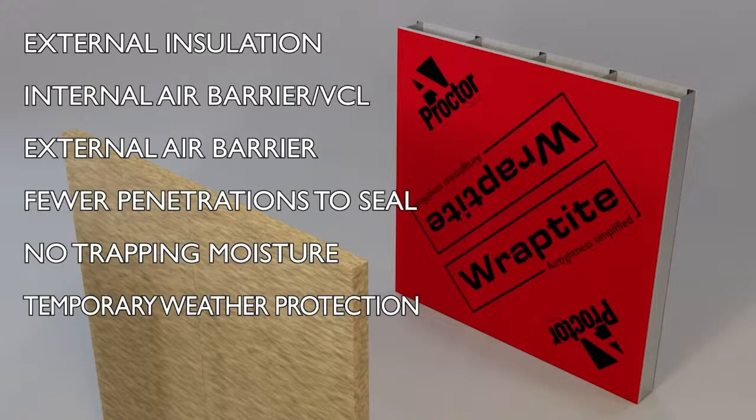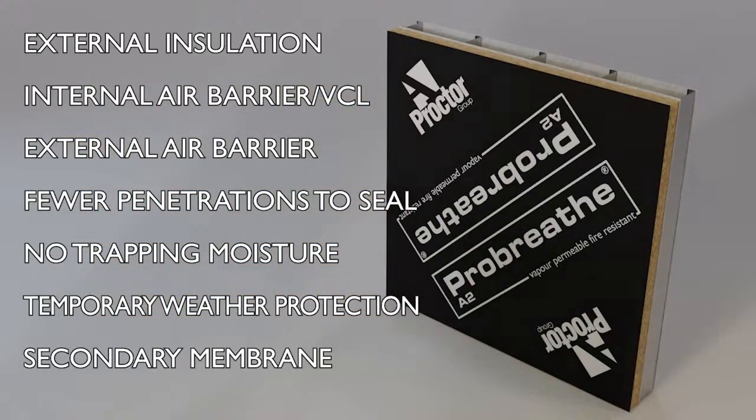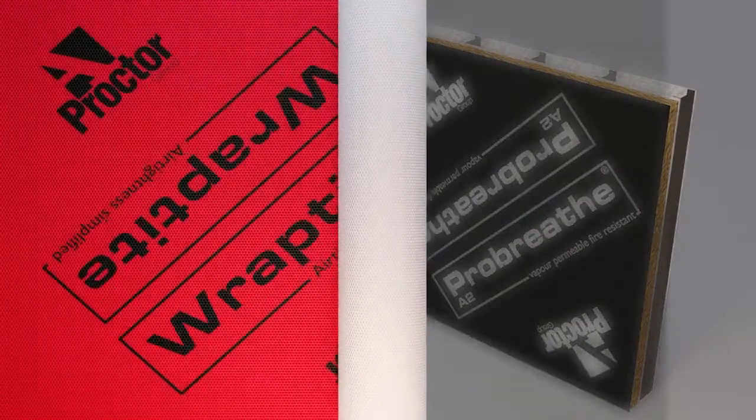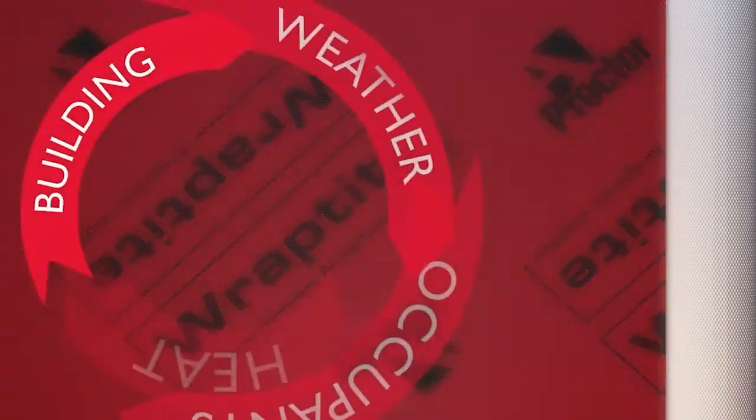In a retrofit context, this weather protection may be particularly important to avoid water ingress into interior spaces, which may still be in use or partly occupied during the upgrade works. On the outside of the insulation, a secondary membrane like the ProBreathe A2 can provide additional protection to the insulation, further limiting air movement and ensuring as-built performance is consistent with design targets. So we've seen how the various aspects of these construction types affect moisture control, and how some of the inherent problems can be designed out.